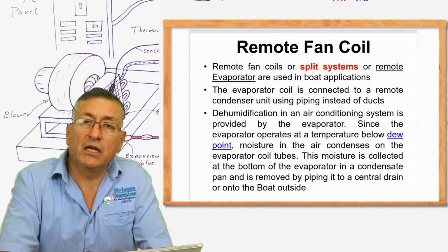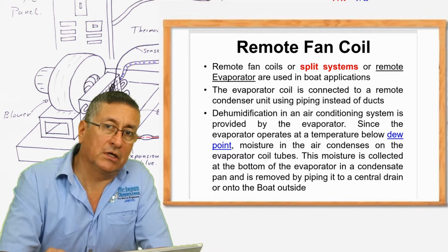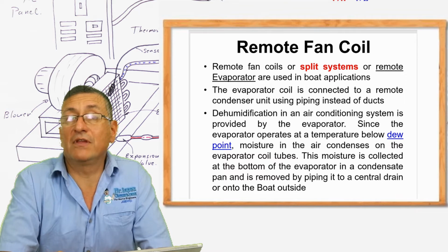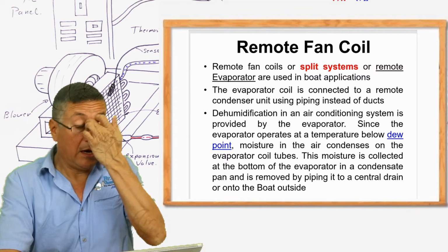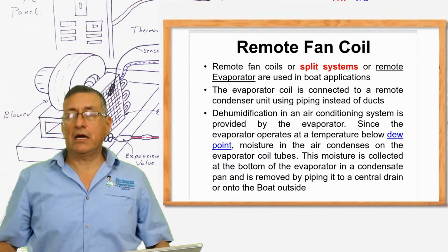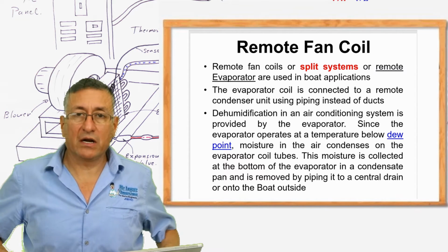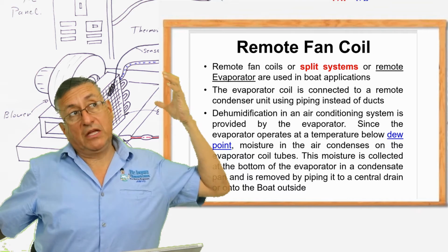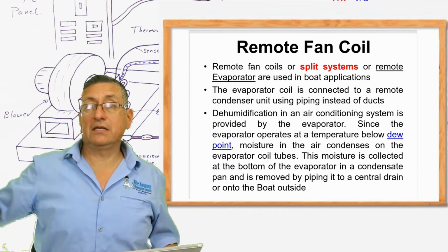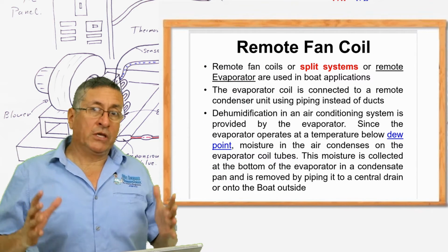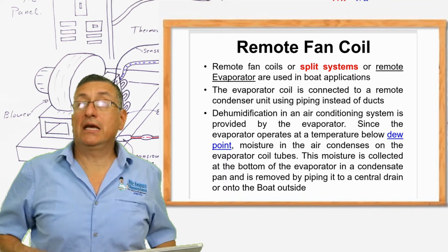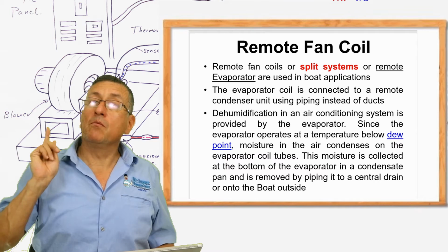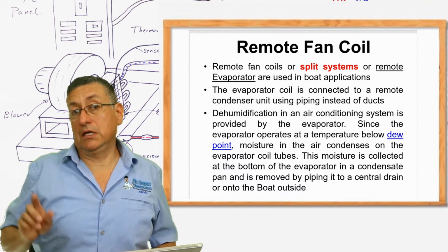by foam in order to avoid condensation and in order to keep the temperature of the refrigerant inside of the lines properly. In split units, I am going to explain later in the chapter when we recover the refrigerant, depending on the distance between the evaporator and the condenser, when you recover the freon, you need to take that distance into consideration, because probably you need to add more refrigerant, because in the pipes,